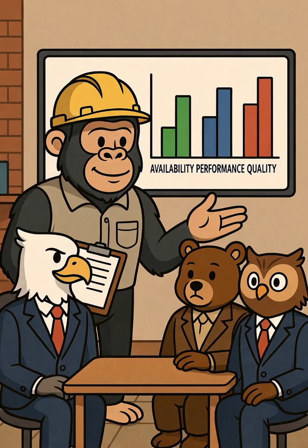Third, OEE is used to track improvement over time. Did that new maintenance program actually reduce downtime? Did the operator training improve speed? Did the quality initiative reduce defects? OEE gives you a single number that captures the overall impact. And finally, OEE helps prioritize resources. If machine X has 50% OEE and machine Y has 80% OEE, you know where to focus your improvement efforts first.